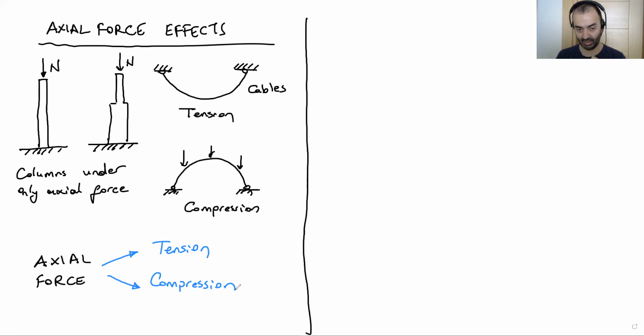We calculate the stresses under this loading condition. If my calculated stress is less than allowable stress, remember what the allowable stress is. The allowable stress is the maximum stress we can reach on a structural system. If our stress is less than that top limit, our structural member works well under that axial force condition.